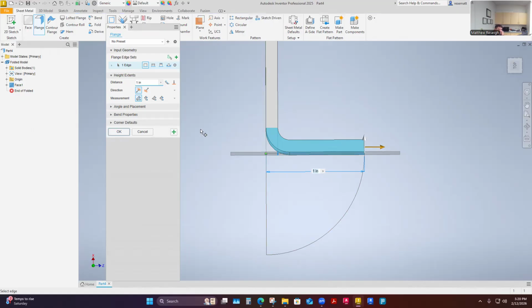And I can change that by this next option. That's because this one is from the intersection of two outer faces. That's maybe what the default location for the measurement was going to be. In ours, we actually changed this to two in the book. So he just changes that to two, and if I change it this way, we'll notice how that dimension pops different. See, now I'm measuring from an inside, and the overall length is now going to be my 2